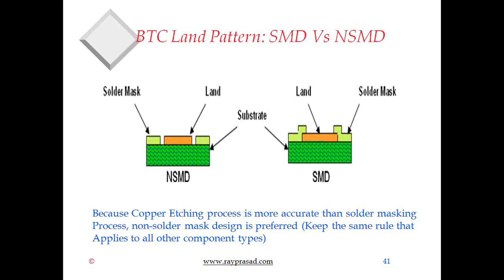And in some cases like BGA, solder mask defined pads have even lower reliability, because where I'm pointing out where solder mask meets the pad, that's sort of like a ready-made crack, and it's not a good idea, especially for BGA. But it's not a good idea for any type of component.